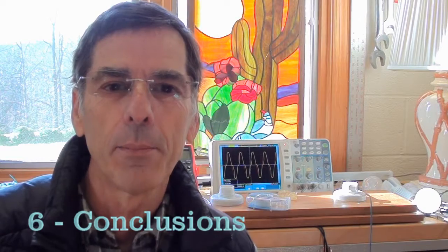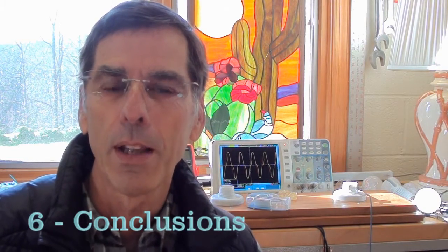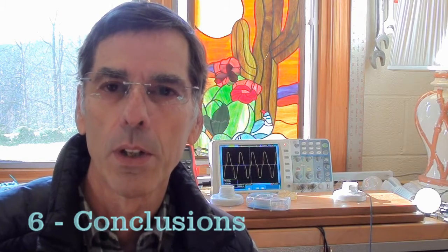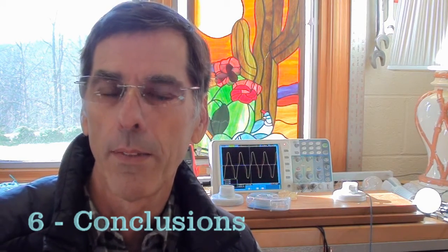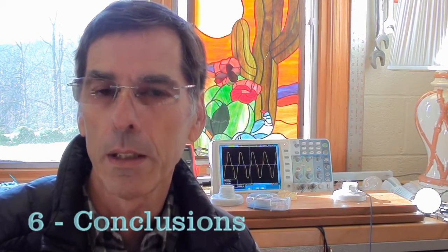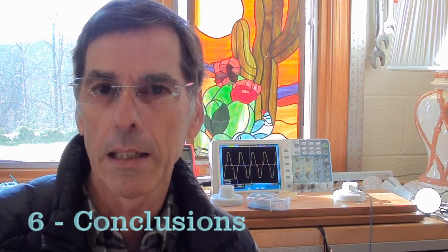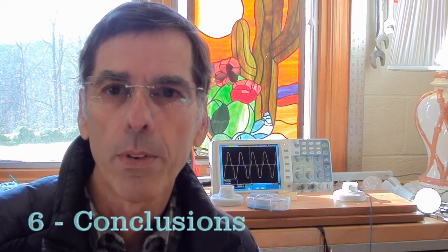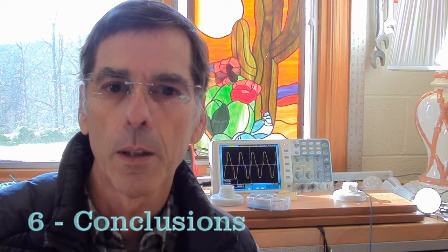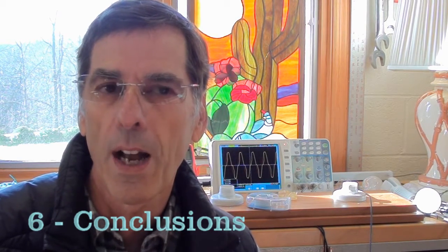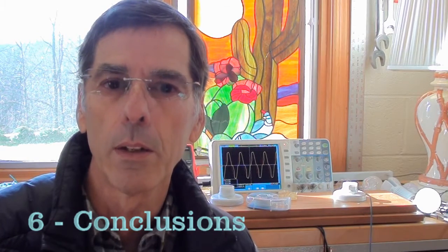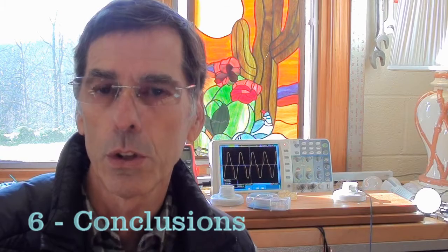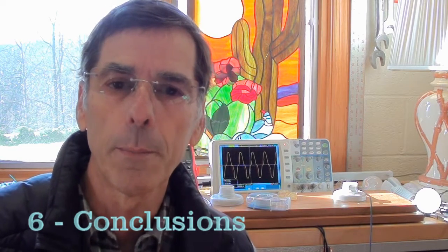Well, basically, dimmers are dimmers. They really haven't changed effectively all that much since they came out in the 70s. Some front-end features, but the actual switching and dimming is still done with a triac, and it's not that much different. There is no perfect dimmer that I found. All of them will lose 5% or more of the brightness on full brightness. That's a feature that really should be implemented, in my opinion.